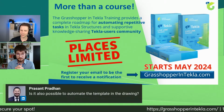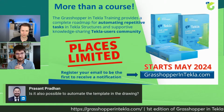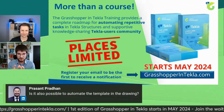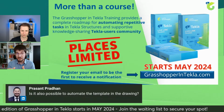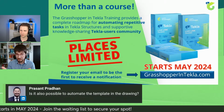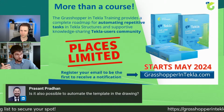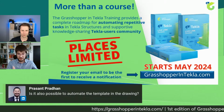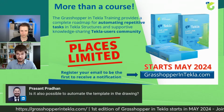Cool. Is it possible to automate the template in the drawing? Yeah, and at the end of this presentation, there are some limitations of the link, mainly about the Tekla Open API. And the templates, unfortunately, are invisible to the Tekla Open API, so the Drawing Link itself will not return any information about the placement of the templates or their sizes. Those objects don't exist in the Tekla Open API.